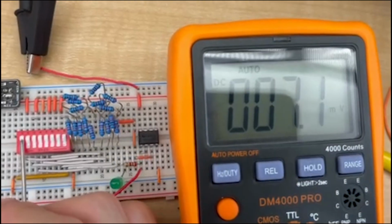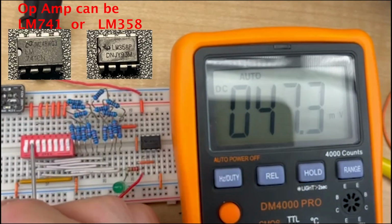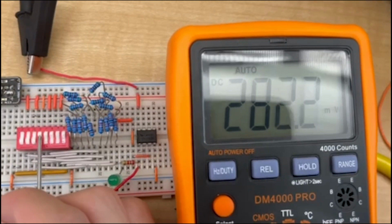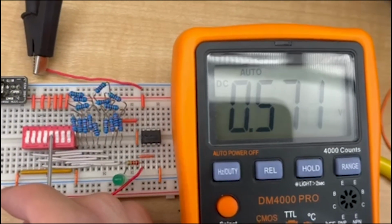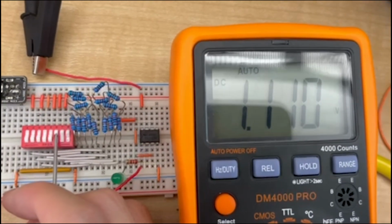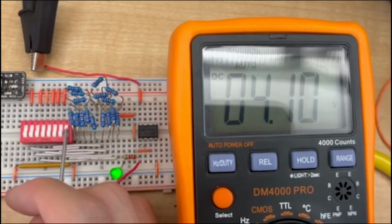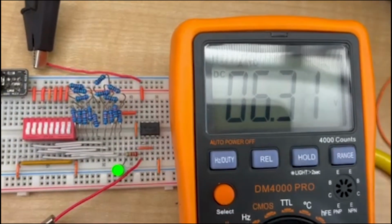This is my breadboard prototype working with the op-amp. When I flick these switches on one by one, the voltage goes to 1, 3, 7, and then so on until 255 out of 256. And it goes until it caps at 6.3 volts due to rail-to-rail voltage swing.